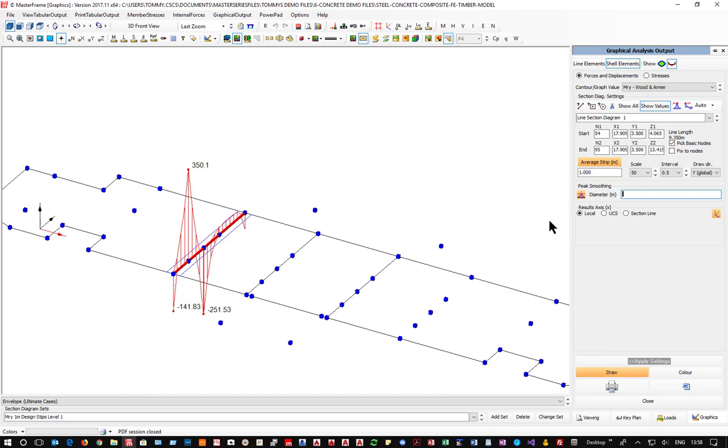So with our columns underneath, on a 4 by 5 meter grid, we could take a 2 meter width. Now, if it was BS, you would take that 2 meter width, but you would design the 1 meter width for its reinforcement, and then the other 2.5 meters external to that for a different reinforcement. I could not see anything in the Eurocode that said you needed to do that restriction.